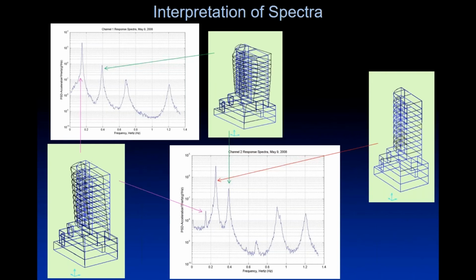This is a building on 2nd Avenue which had a big crack at the back of it. We monitored continuously for 2 years in positions up on the roof. Just 2 positions, because what we do is we go in and take a baseline. A baseline involves us saying, okay, we will measure in our reference positions, but we will take a traveler accelerometer and we'll put it in various different places in the structure, and we'll measure the vertical profile of displacement under random excitation. That's very successful.